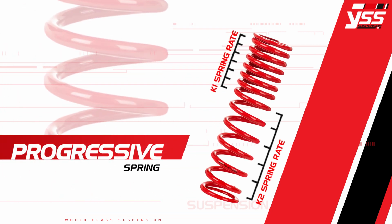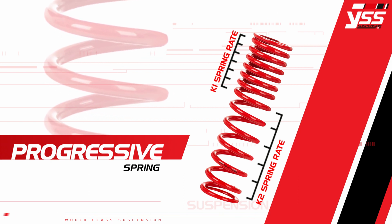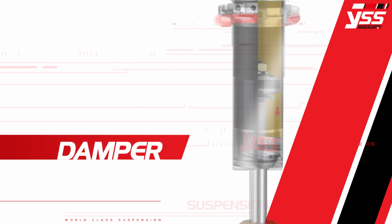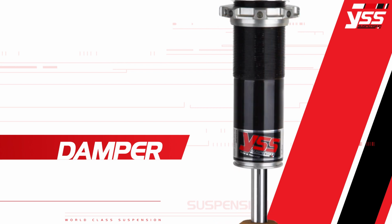The narrow coil spacing, the soft part of the spring, is activated first and then gradually goes to the harder part of the spring. Damper. Hydraulic oil will flow through holes in the piston, which has viscosity, when pressing in compression and rebound. The resistance is controlled by the hole size of the piston and the shim hardness.